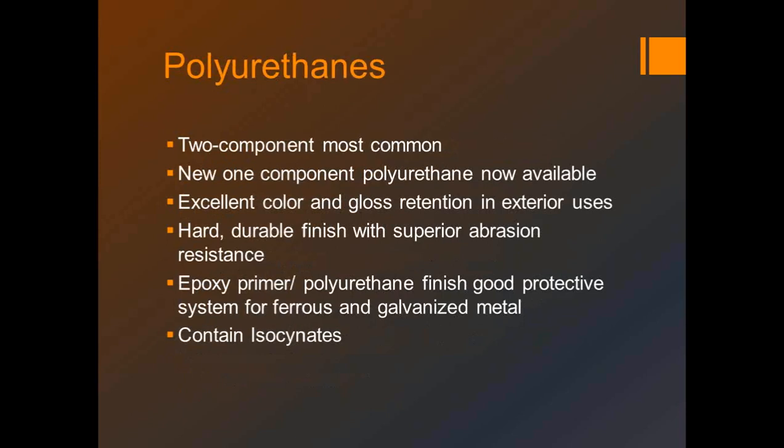You had something, David? I liked your idea here. You mentioned the epoxy primer and the urethane finish coat, and that has really been our go-to system for corrosive environments anywhere along the eastern coast, Gulf Coast. So it's anything metal exterior that has any possibility of corrosion.